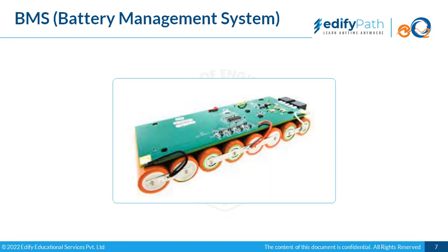Typically, in a battery pack, the smallest unit is the cell. We combine cells in parallel to form modules, and these modules are then connected in series. From each and every module we have a control connection that is connected to the BMS, and through this the BMS monitors each and every cell in the module.